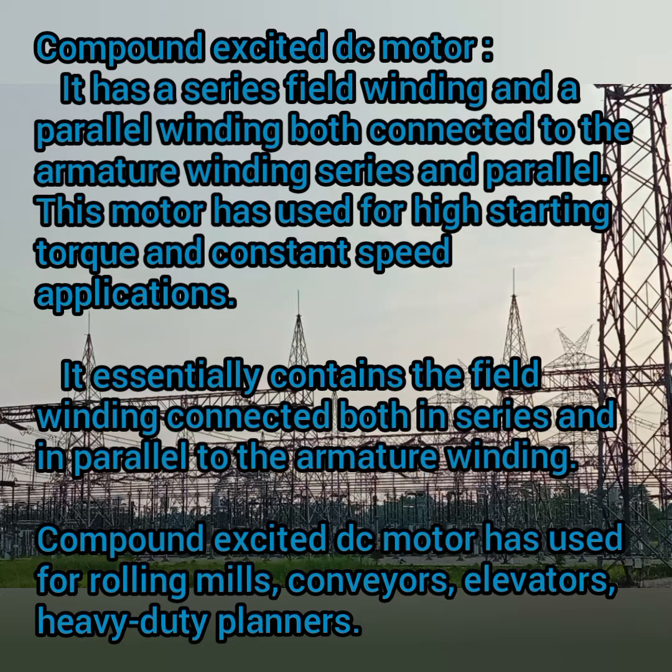So it is mainly used in most of the industrial applications like rolling mills, then for your conveyor belts and elevators, heavy duty planers, and also cutting machines, because it is having a high starting torque and also the speed of this equipment can be easily controlled.